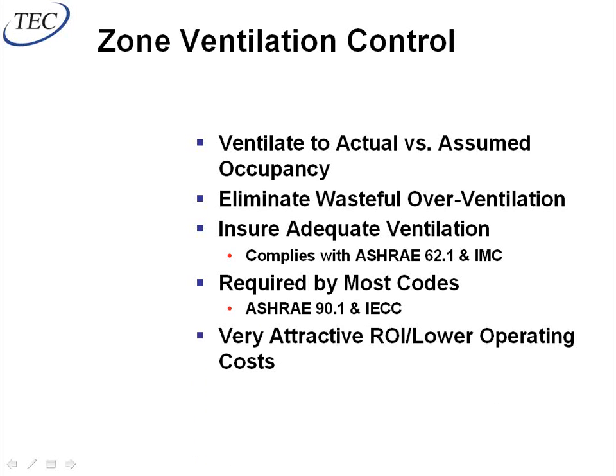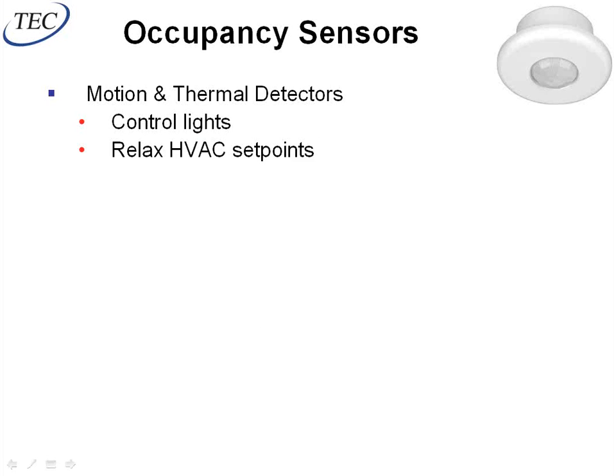The return on investment is very, very attractive. We do a lot of energy-saving technologies here at TEC, ERVs, variable refrigerant flow, chill beams, all this stuff. I can't think of too many things that can save as much energy for as little investment as a CO2 sensor. Maybe a programmable thermostat and an economizer. Those are the first two things you put on. When you're ready for your next third technology to implement, CO2 is probably the next thing you should think about. So programmable stats, economizers, and CO2 are the order of fast payback of things you can do real simply.